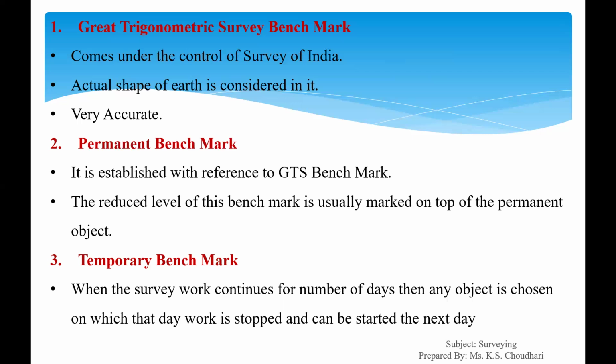So to stop that work, we take a reading on any object, and the work is stopped. That reading is nothing but the temporary benchmark. From that reading, we can start, or we have to start, the next day's work.